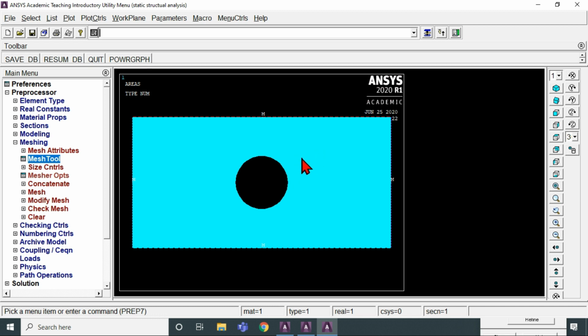So individual 50 elements. Now we have to do the same thing for this inner circle also, because wherever there are unsymmetrical shapes, for example arbitrary shapes, we have to capture them with more nodal points. So in that case we have to give more nodal points over here.